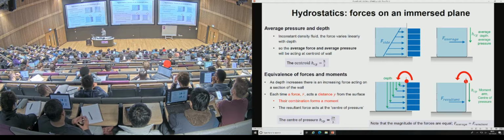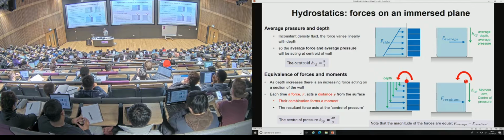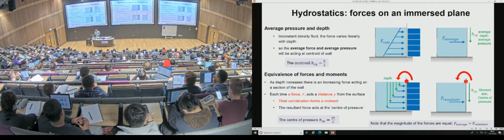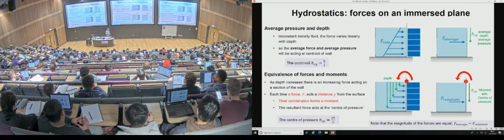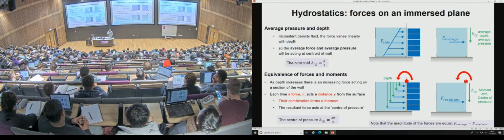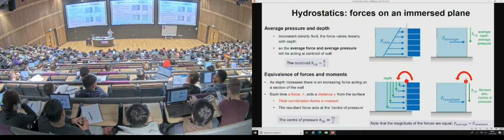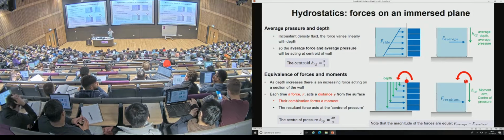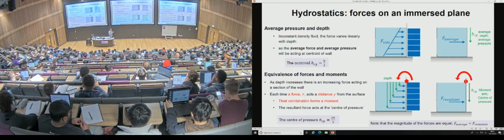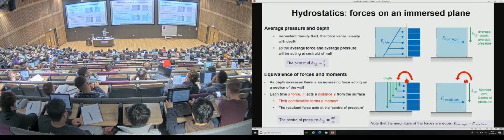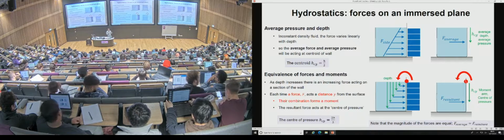Yes? How do we find the resultant? So the easy way to think about it is the resultant is simply the pressure at the halfway point of the tank, the average force, because the individual forces are purely a function of their height below the surface. But remember that the integral of those forces, times its moment, is going to result in a moment which is a distance below that location.